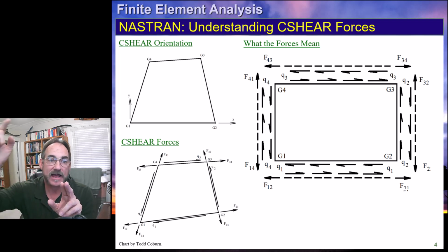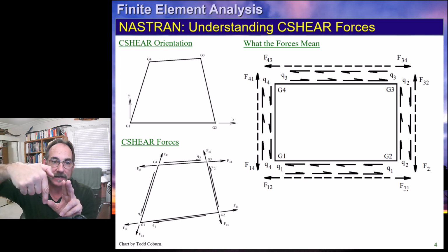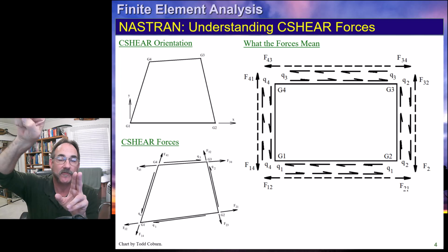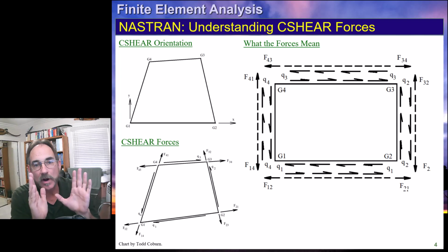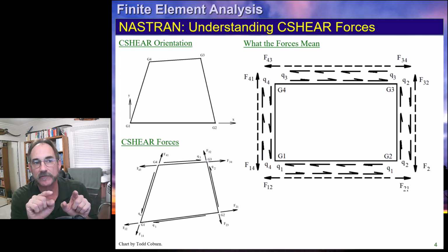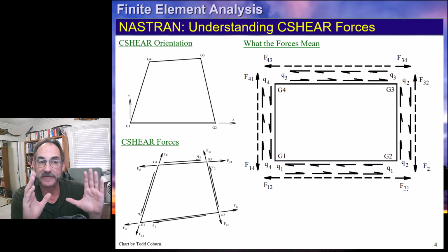At 2, we also have F2 coming from 3. We're missing the 3 subscript. F3 coming from 2. F3 coming from 4. See that? So each rod has not only those corner forces, but also the corresponding shear flow in the equal and opposite direction. This is going to end up giving us equilibrium on all of the members.